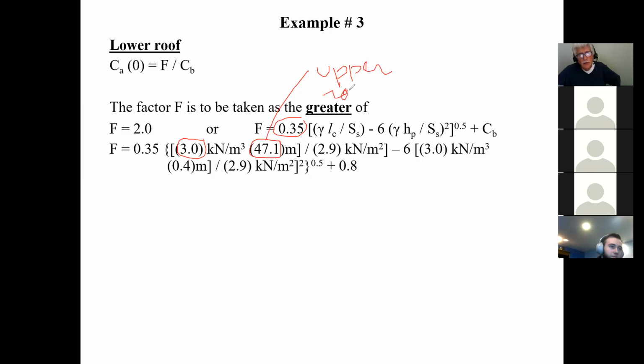And we did that already when we wanted to calculate the CB value. And of course, this we got from the table, okay? Now, again, the unit weight of snow, okay? Now, HP, of course, you see on the drawing, you go look at the architect and you look at how high this parapet is, and that's the HP value. And if you look at the sketch, I gave you a value of 16-inch parapet, which is reasonable.